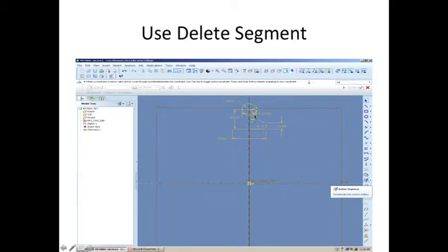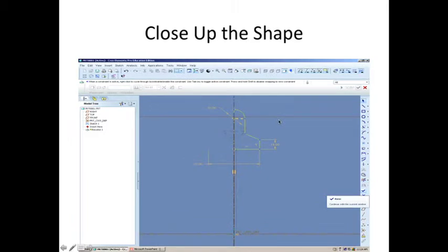My next part was I made this circle at a diameter of 30. From there I made a line from the edge of the circle going straight down, and then I used my delete segment command to delete everything that was in the middle so that it could look like this. And you're going to want to delete everything, because if you don't, then the revolve won't work.